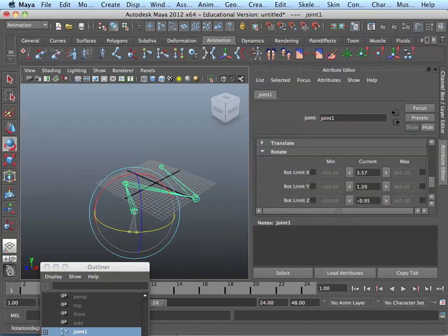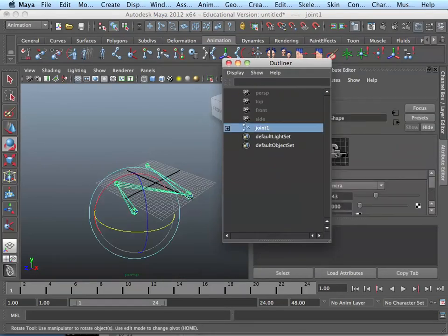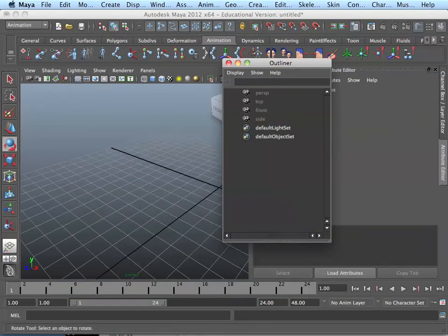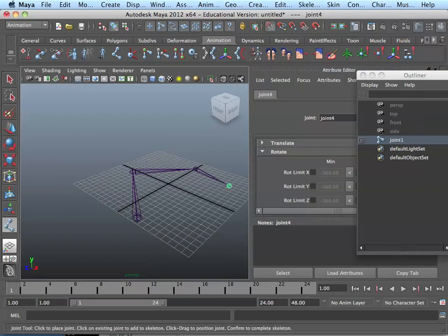Well, it's a little bit off because I didn't make it flat. Hold on, let me do this again so it actually works. So I'm going to turn the grid snap on. Also, it helps sometimes just to do it in the orthographic view. So if you do it in the top view, you know it'll be flat. So actually, let's do 3.